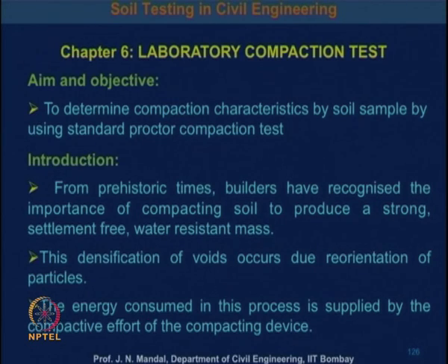So, you need proper verification for the compaction test, and also to check whether the soil has been compacted properly or not. For this, it is very important to determine the compaction characteristics of the soil sample by using the standard Proctor compaction test.